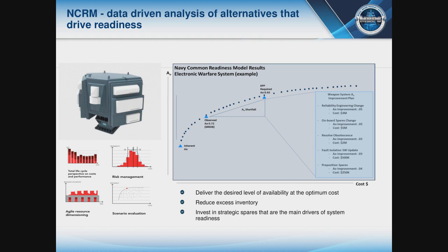And that's when cost is way out far to the right here, where you start to approach the system's inherent availability, right? So the other side of your design parameter is, even if you had a perfect logistic support solution based on the reliability, based on the redundancy, based on the criticality of components in those redundancies, there's some inherent availability you just can't get above. And that traditionally is something less than 100%, right? A perfect system would have 100% A sub O. And perhaps with very, very low logistics delay times and a very, very redundant system, online maintenance and things like that, you get fairly close to 100%. So whatever that is, right? But of course, an aircraft system or a helicopter is going to be much, much less than 100% as an inherent availability. So somewhere along that is a sweet spot, right?